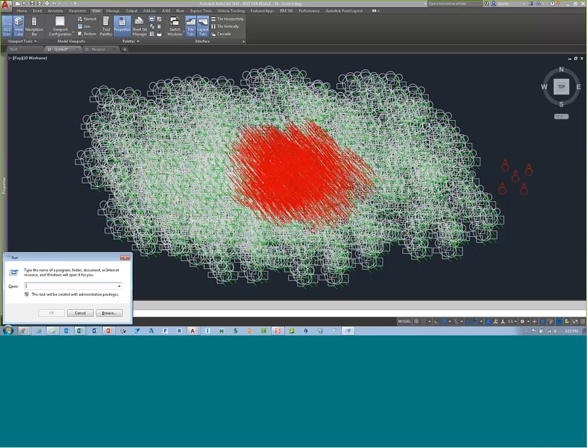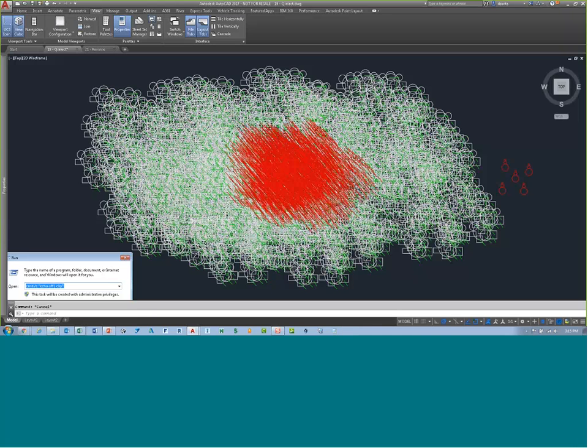So if you go to Start, Run, and you type in CMD space /C echo space off, space, vertical symbol, space, clip. And this is in the tooltip, don't worry. And I hit OK. It basically dumps that Windows clipboard memory, and it makes AutoCAD run a little faster.